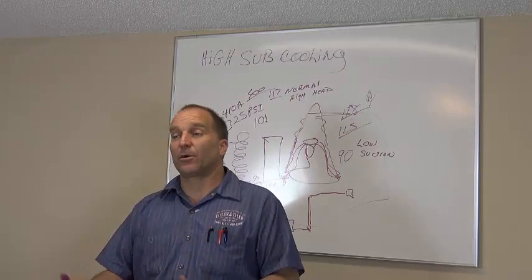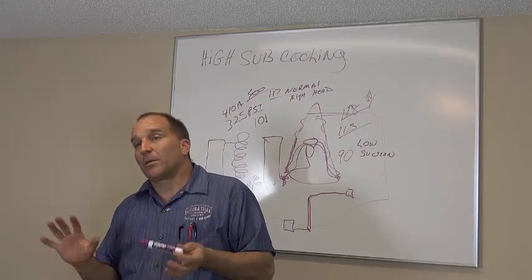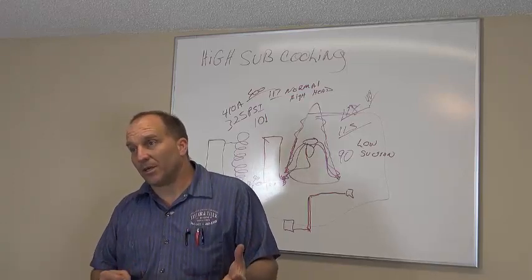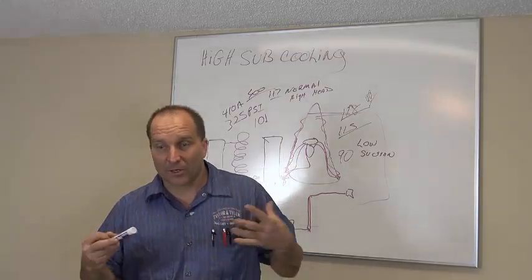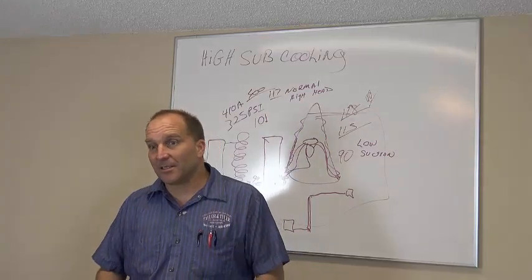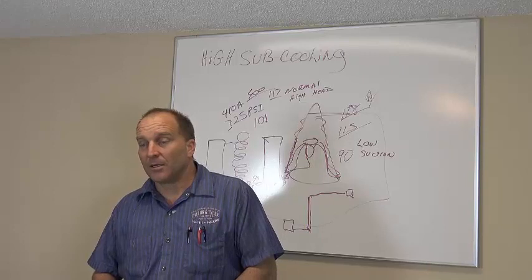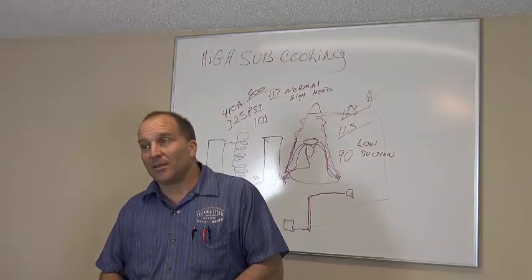Do you have a TXV or a piston? You can have very weird subcoolings with a piston because you're not worried about what your subcooling is with a piston. You are going to worry about your subcooling with a piston if your condenser's dirty. And you should be cleaning your condenser because it's easy to see, and you should clean every condenser that you go to, right? Okay? So make sure that when you go to a job, you are cleaning these condensers.